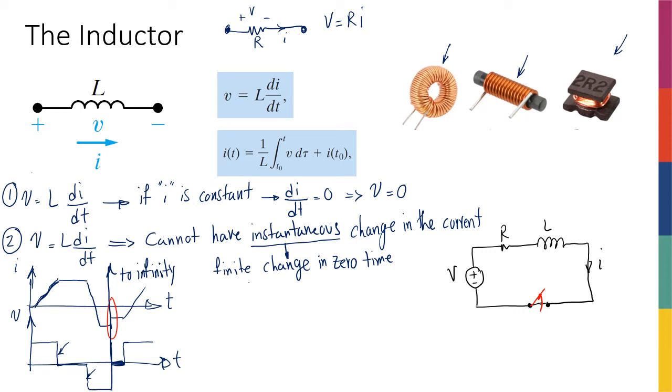You might actually see a little spark in the switch for a moment before everything turns off. And that spark is because when you open the switch, the current cannot go to 0 abruptly. The current wants to decrease and go to 0 in a short time, so the electrons are actually jumping over this gap.